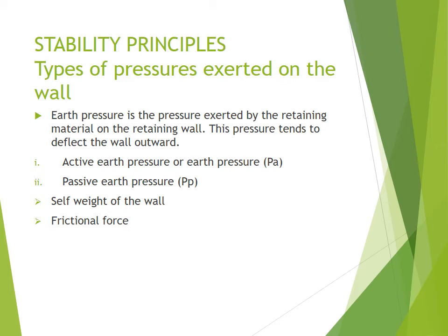Now the active earth pressure, this is the pressure that exerts the force from the retained material. This pressure is increased by any surcharged or superimposed loadings. The pressure is applied for the full depth at the rear face of the wall but increases with depth. It is considered, however, that this can be replaced by a force acting through the centroid of the force diagram.